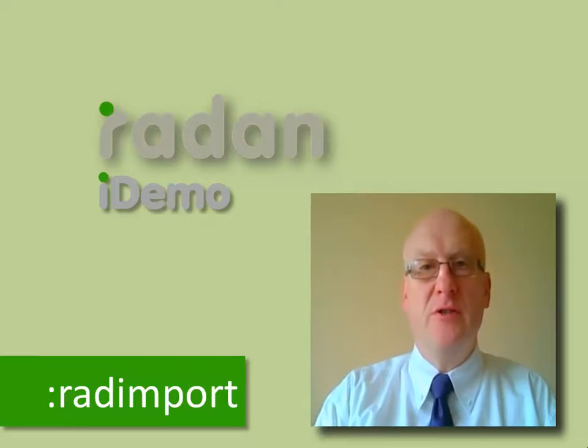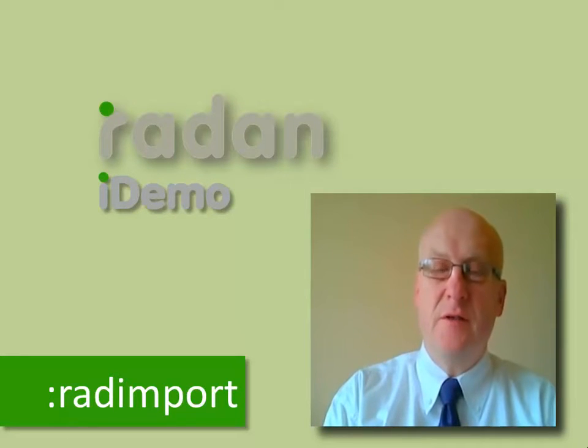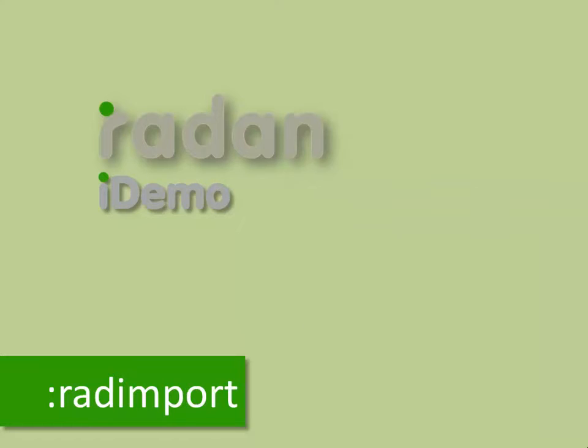Now Radimport is a utility that dramatically speeds up the process of importing 2D data into Radan and preparing it for manufacture. Radimport can read DWG and DXF files, but can also read CSV files from MRP systems, which in turn can populate a nest project with your manufacturing requirements.